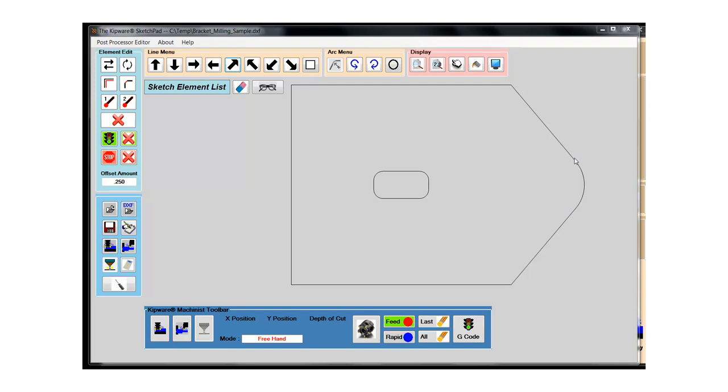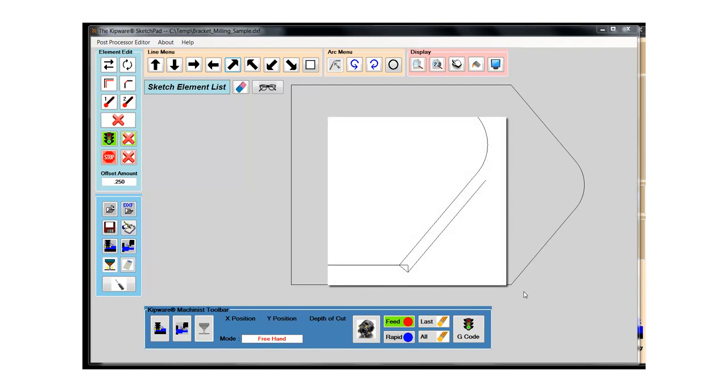whereas these tangency points from the print, we don't know where those are. The only thing we know is this point and the angle of these 2 lines. And that's sufficient in the SketchPad to be able to draw this tool path. So what I want to do is calculate an offset of 255. And you can see on the screen that we have a little triangle there.